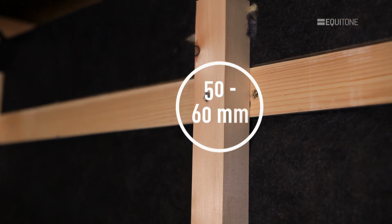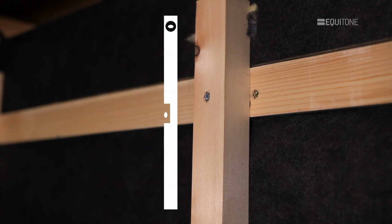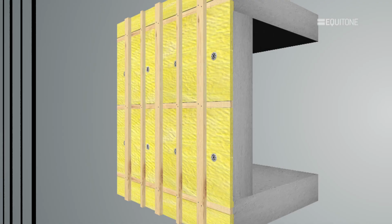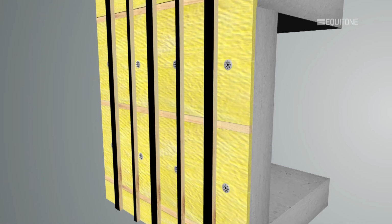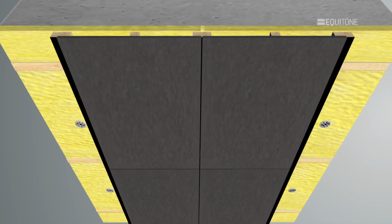Battens used behind the vertical panel joints or at corners should be 90 to 100mm wide, with the other battens 50 to 60mm wide. Ideally, the batten should be smooth on the front face and one edge to ease levelling. EPDM or aluminium protection strips are placed on the face of all battens. This helps to protect the timber and gives an added benefit of providing a black shadow gap to the joint.